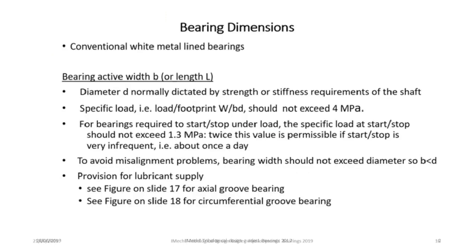The outer surface of most plain bearings is coated with a thin layer of a soft, low melting point alloy, often called either white metal or babbitt. This alloy can include tin, lead, zinc and bismuth. Not so much lead these days. It is there to act as a final protection against dramatic failure, if, for some reason, the lubrication system were to fail and the bearing becomes starved of oil. The alloy softens or melts and prevents gross seizure and potential dramatic machine failure.